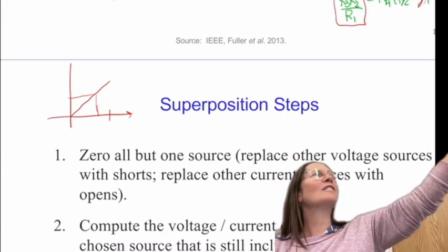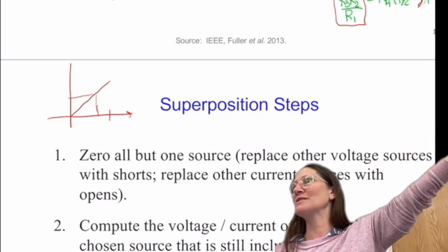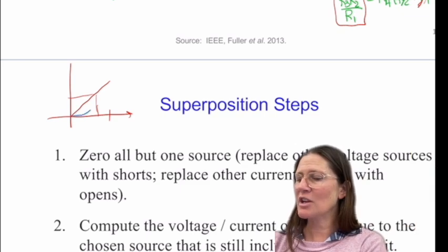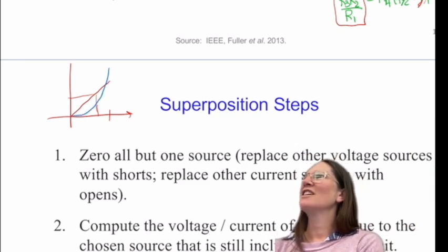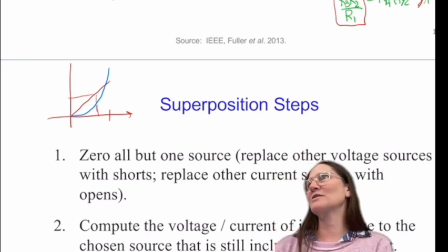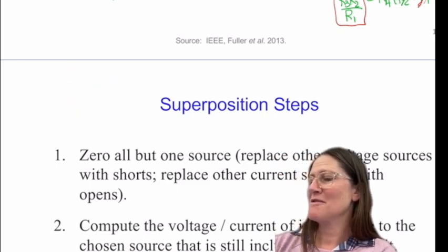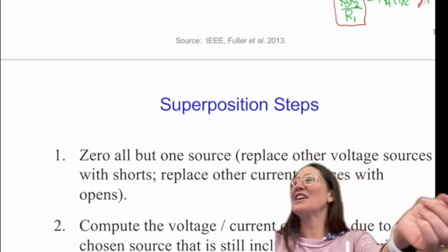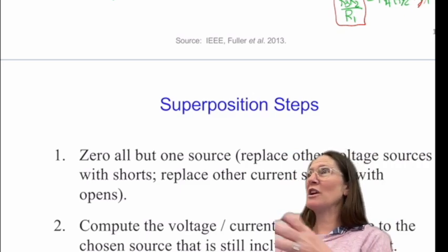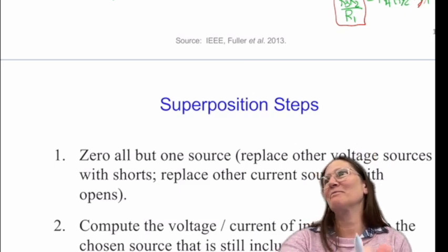You put in 4 volts across a resistor, you get a corresponding exact amount of current. A nonlinear device actually has a curvature to it, and so it doesn't respond exactly the same for every input. That's the difference, and we're not going to talk about that in here. That's a little bit more depth than you need. There are ways of making a nonlinear device linear and then using the same techniques.